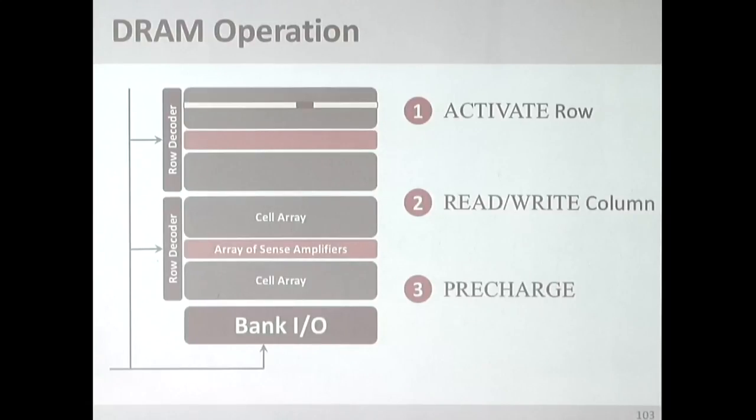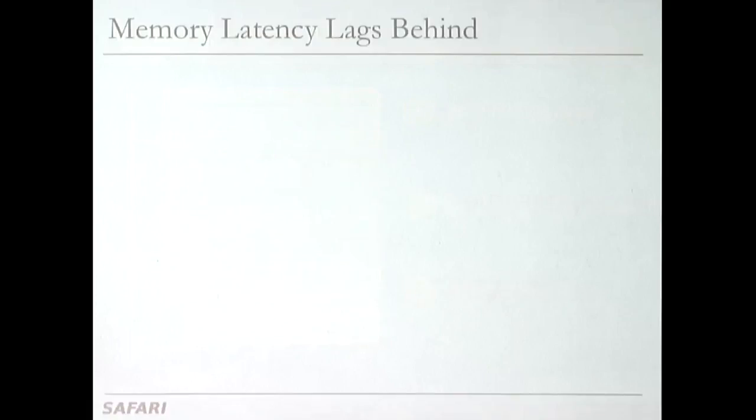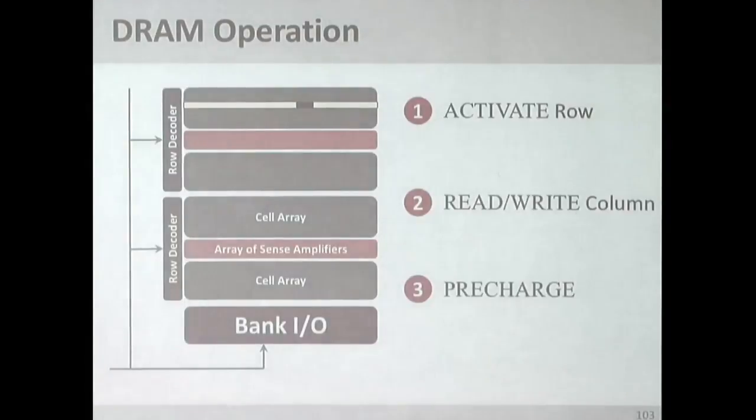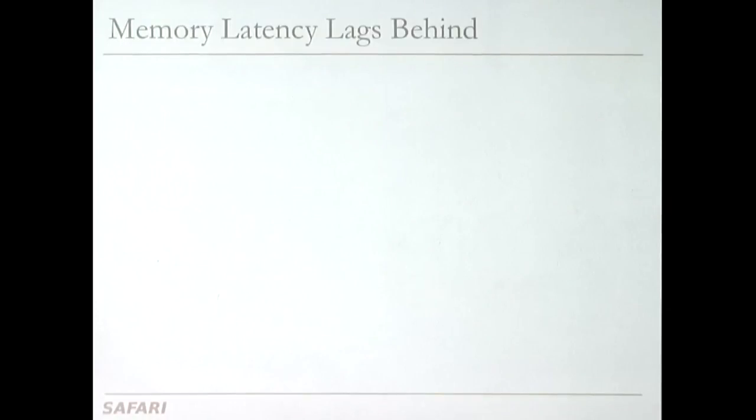The abstraction that we had in a bank is different right now. We went one more level down. The reason is you cannot have those local bit lines long because that's expensive and also high latency. But even this is high latency, actually. Now we've chopped up a bank into, in this case, 2, but really 32 subarrays. But even this is high latency for multiple reasons. One is the subarray access latency, the sensing latency, and that tends to be the dominant one. But then there's also the latency to drive the signals out of the bank. So we're going to talk more about that.